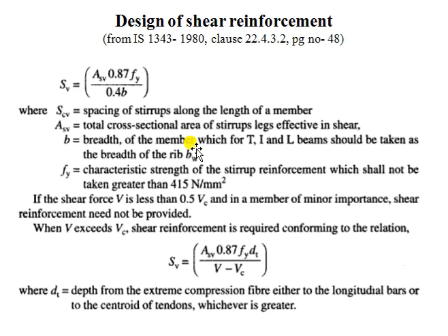To design the shear reinforcement, the formulas are the same as what we have used in the previous problems. Here you need to remember only these equations, that is, for spacing of the stirrups, this equation and this equation. These equations are given in the code book. So it is sufficient if you remember the clause and page number.